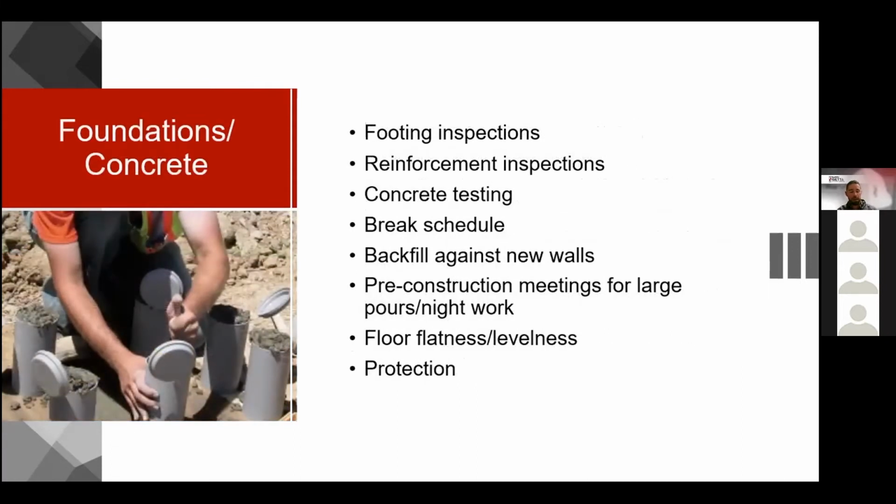And then typically the next step, we'll start digging out and we'll be putting in foundations and concrete. Footing inspections, we'll review the depth, width, again, the soil bearing, any over excavations needed, backfill or form inspections. And then there's reinforcement inspections: bar type, size, lapping, clearances, just general layout. Concrete testing, field concrete testing, we'll check batch tickets, we'll do air tests, slump, temp, cylinders. Eric, Brian, and James are going to be helping us out with that moving forward here tonight.